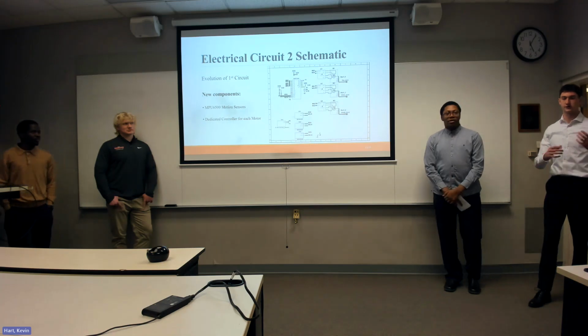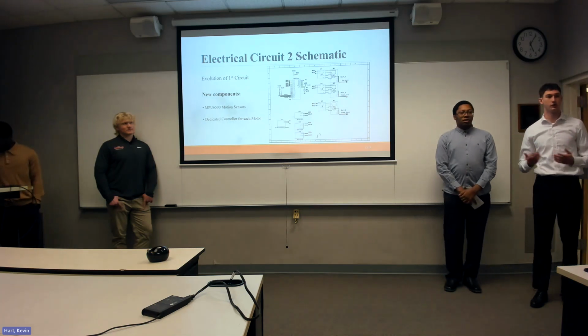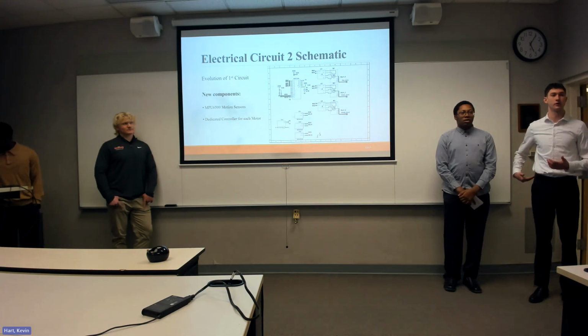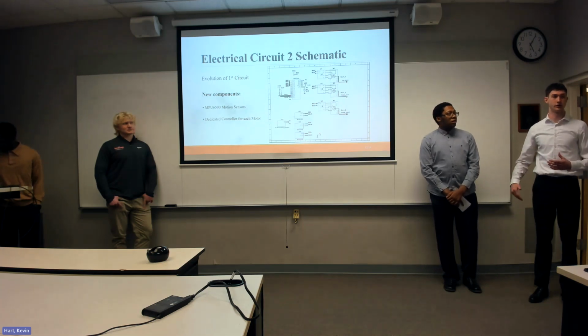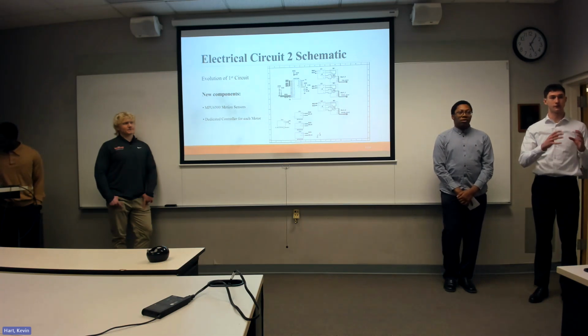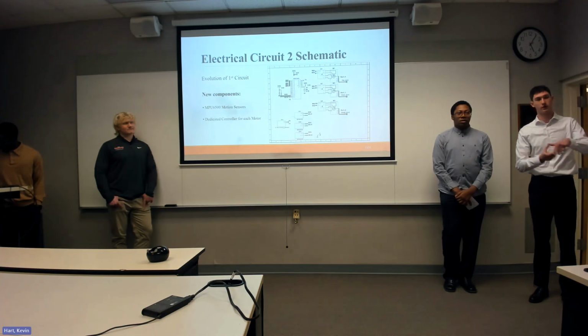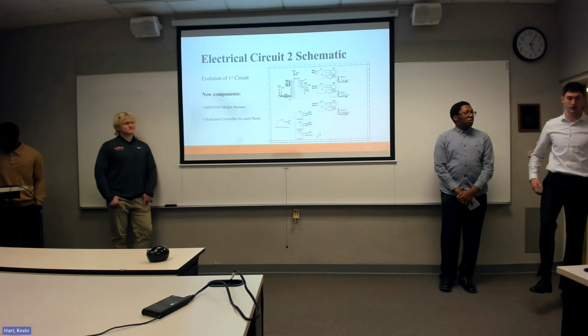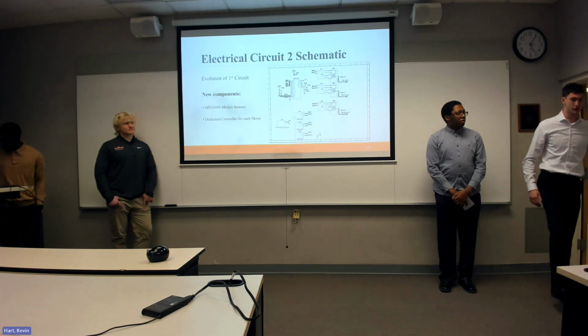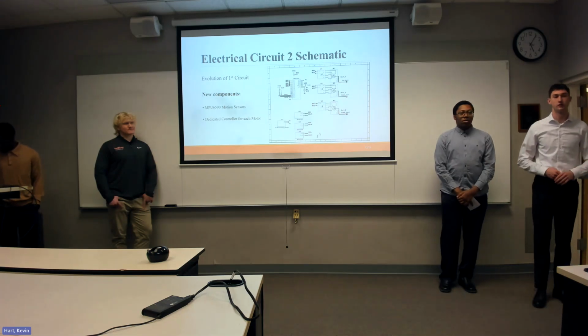I mean, the whole process is that we take in the position data, put it to the inverse kinematics, and then we're able to get all the angles of each joint throughout the whole walking cycle. And then from there, that data gets inputted into the control side of it, and then it outputs replicating each angle to each time step of the walking cycle.